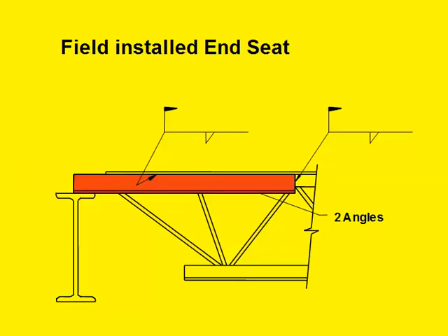This drives my joist friends nuts, but I like to do it because I like to drive people nuts every now and then. I will actually have specified a joist with no end seat. And this way you see if there's no interference or very little interference, the joist really is only that long. So now the erector can build a scaffolding or something. He can put it up in the air, and then we put on the seat. And it goes in easier.